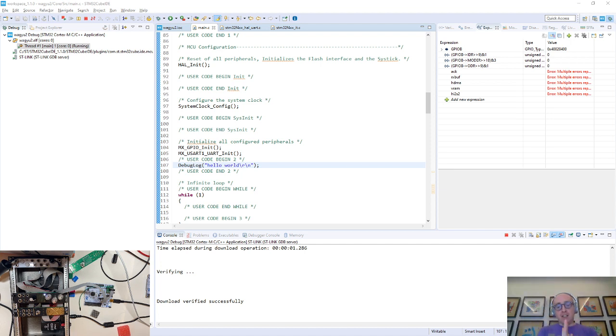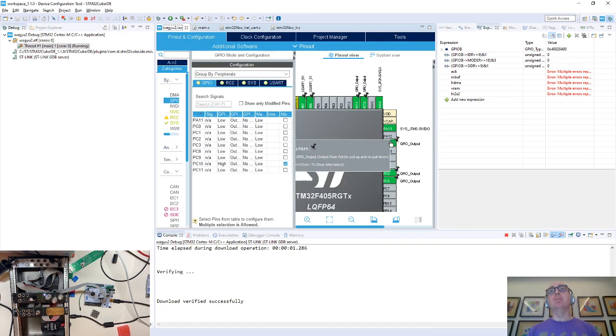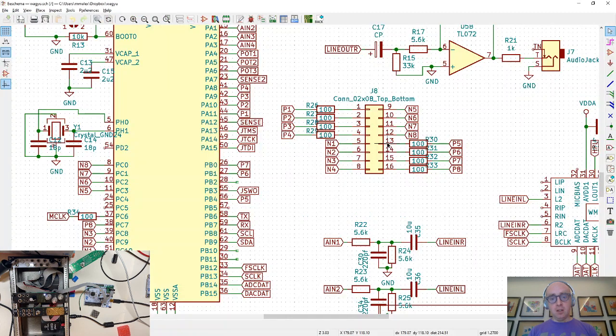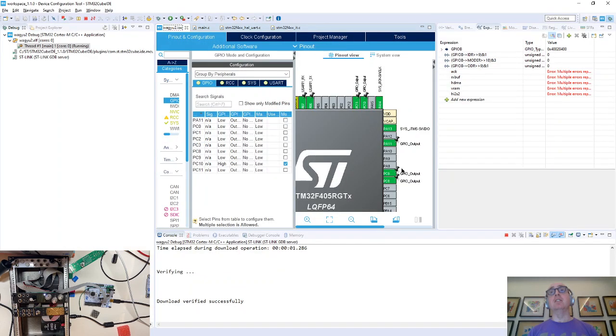Let's do a row of LEDs, but also let's do PWM. So that's why I didn't bother setting up all the Ps. It was PA11, I believe. So now we are going to quickly set them up. I happen to know, because I designed it this way, that P1, 2, 3, 4, and 5, 6, 7, 8, I chose to be pins which had timer capability.